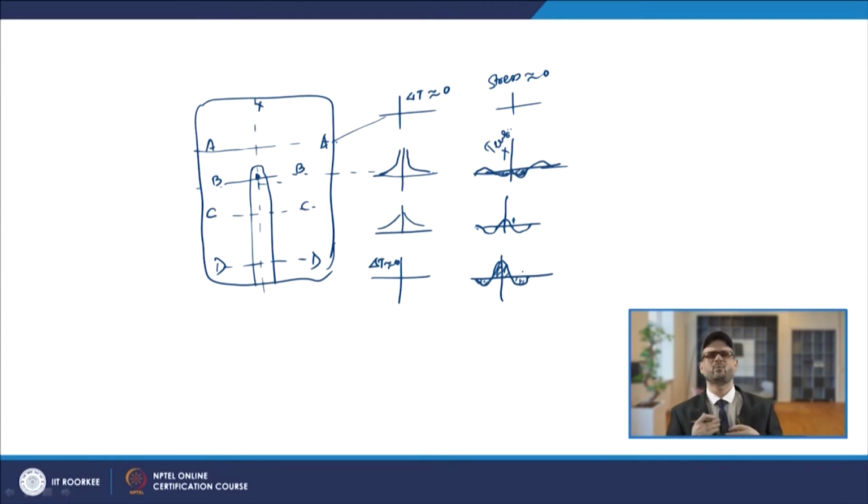So, basically, what we wanted to know is that when we talk about the mechanical stresses, in those cases you have expansion as well as contraction going on. So in those cases the stress pattern will be changing, and that will be the development of the residual stresses. If you talk about the other residual stress, that is your metallurgical residual stresses.